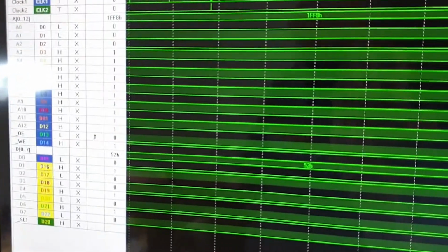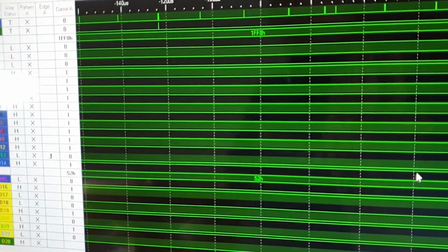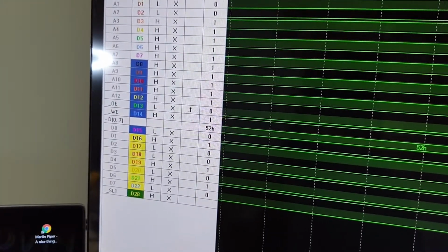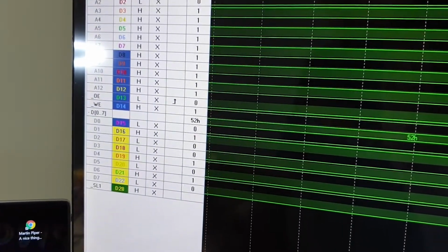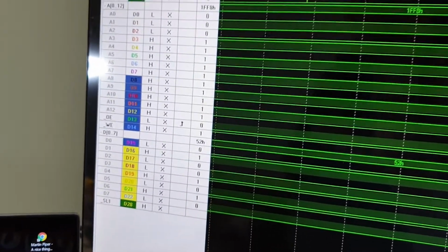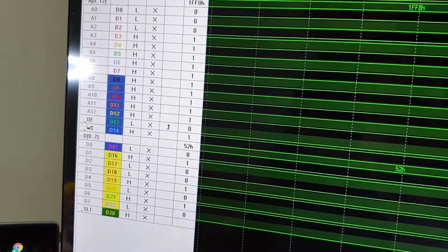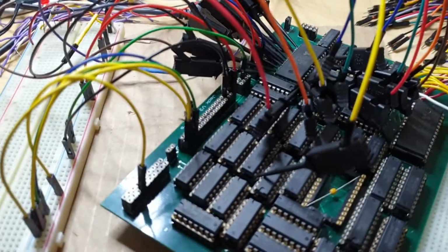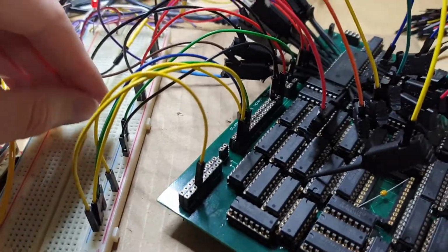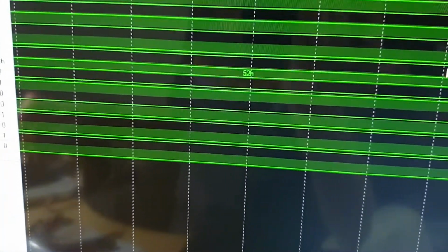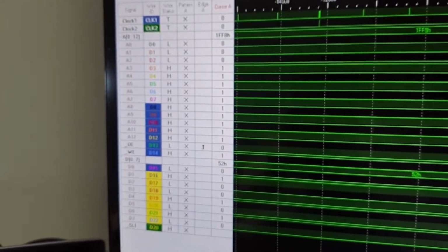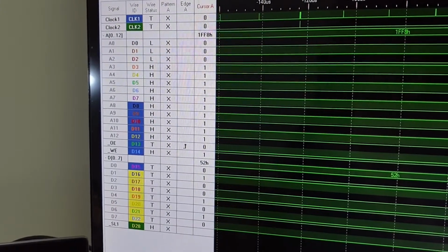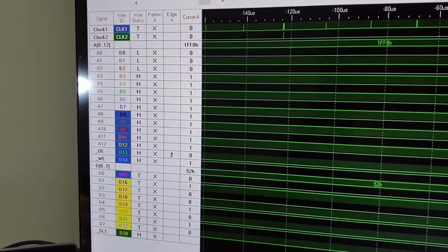1FF8, if I remember correctly. Yeah, 1FF8. Yes, I think so. So then what I do is that if I set the corresponding extended memory bus bit to be high, which is going to be that one there, then what I would expect to see is that I want the same memory address to be presented, because I'm now switching from the internal to the external. So there we go, it's the same now.